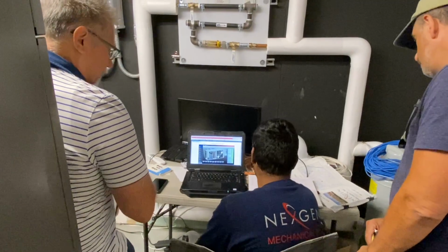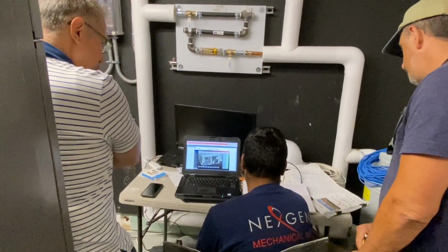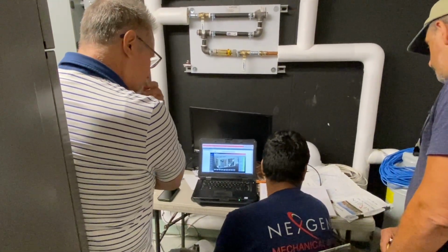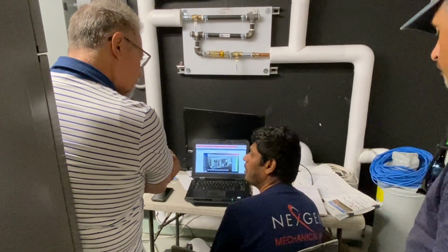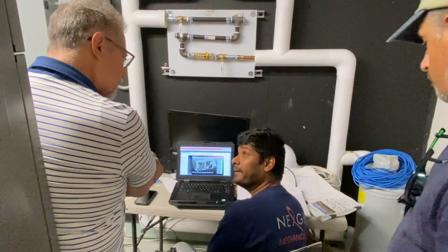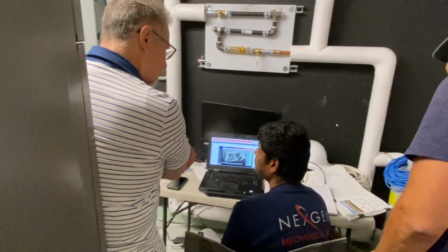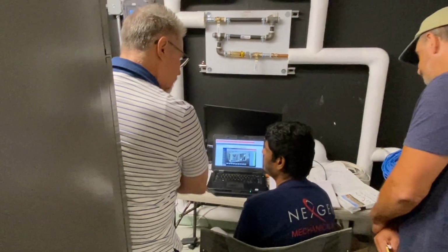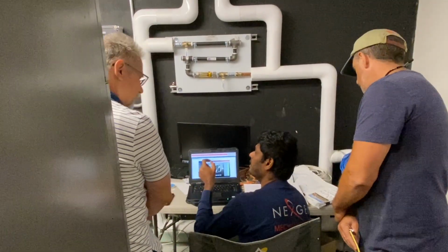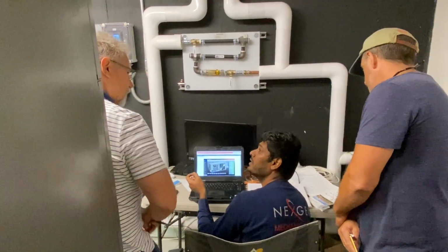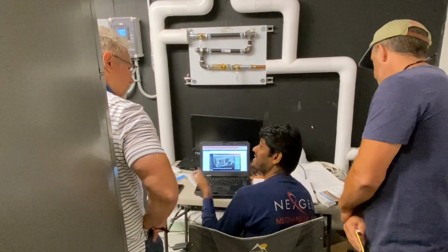The other thing is I'm trying to tweak some set points on something called a dynamic temperature band. What we are doing is trying to change the duct static set point during the course of operation. It's not static.